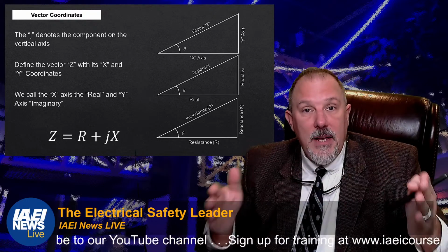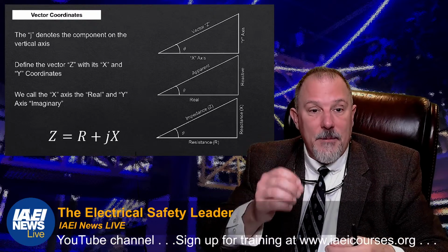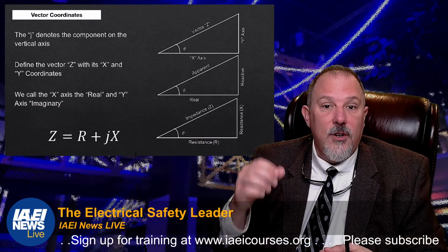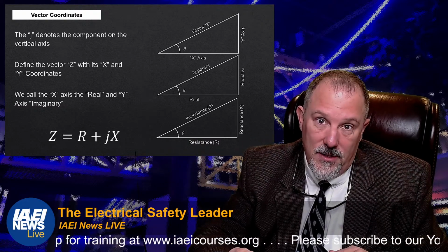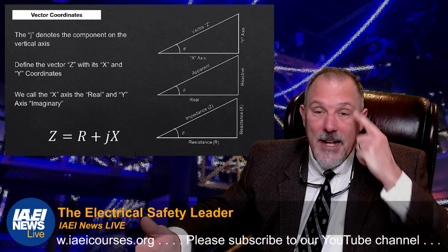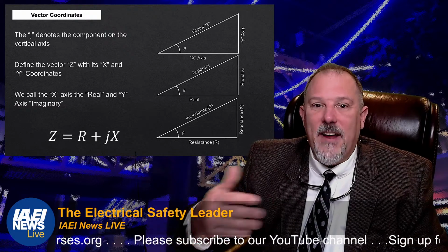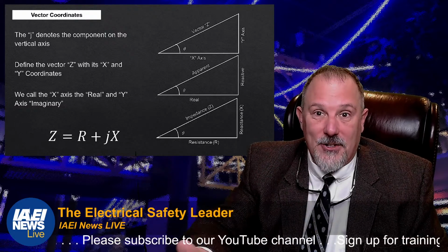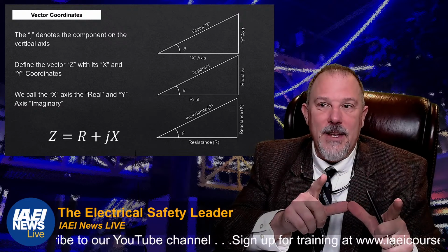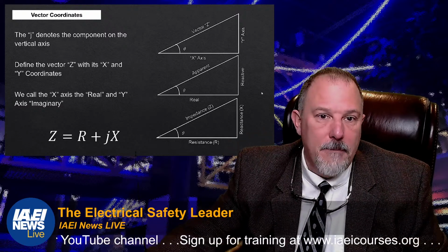And based upon the impedance values and establishing the amount of inductance to resistance, I know what my power factor is, which helps me understand my energy usage, right? And I could lower my energy bill if I know my power factor. If I want to do power factor correction, it all starts with the single line and this impedance diagram.